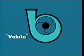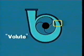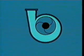It enters a specially designed area of the casing known as the volute. The volute is wider at the discharge nozzle than where the fluid leaves the impeller. There's more space, which causes the fluid to slow down. Its velocity decreases. The fluid gives up some of its energy.